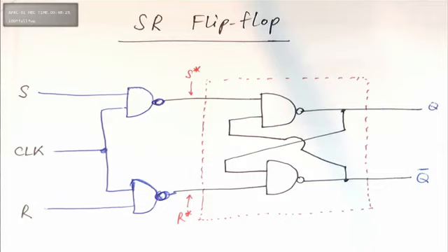So basically what we've done is the moment you add clock, which is control, into your circuit, you now have a flip-flop. A flip-flop is a circuit which is able to store one bit of information, but with your control. You instruct it saying, okay, save now, or recall now. When do you want to recall? You press the recall button. Recall now, okay? All right, now let's do the truth table.